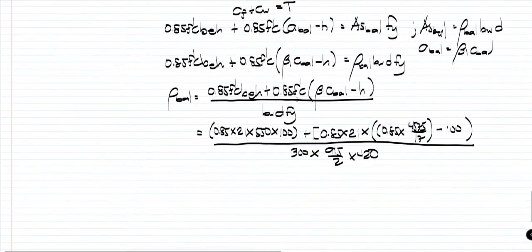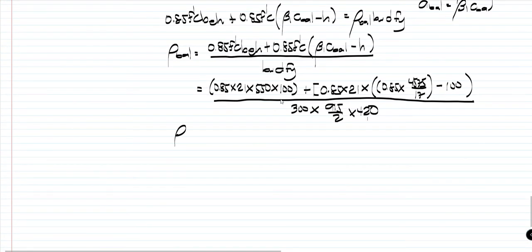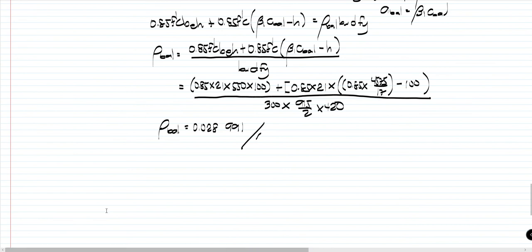So calculating our raw balance, we have here 0.028991. Ito ngayon yung ating balance steel ratio. Now dako tayo dun sa maximum steel ratio. So sa maximum steel ratio natin, syempre kukuha muna tayo ng Cmax, and probably will arrive with the same equations as this one. So ang maiiba lang is yung Cmax kasi natin is on the part of the 3/8.